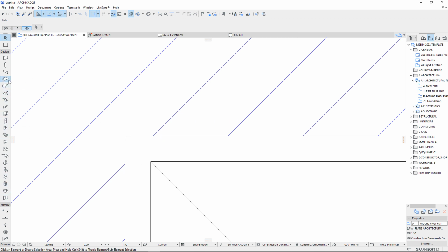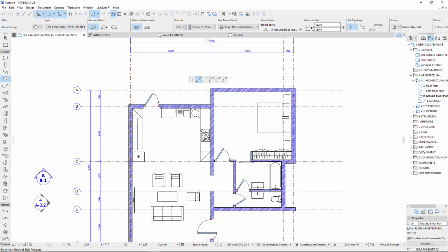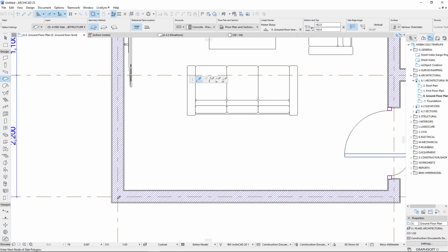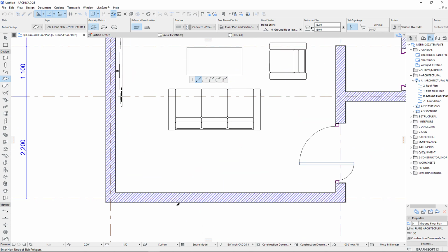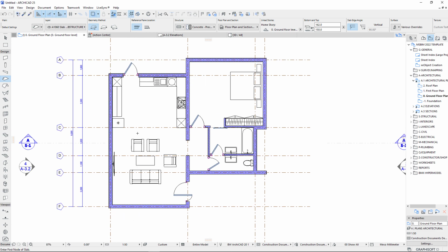So if you bring on your slab, I'm going to pick only the core of this brick or the wall structure instead of the plaster. I don't want to pick the finish because the finish comes after casting your concrete slab. So yes, I'll just use this one for that. You can place this point by point, or you can speed up by using the magic wand, pressing the space bar and holding to click on the space like that, to automatically place your slab.